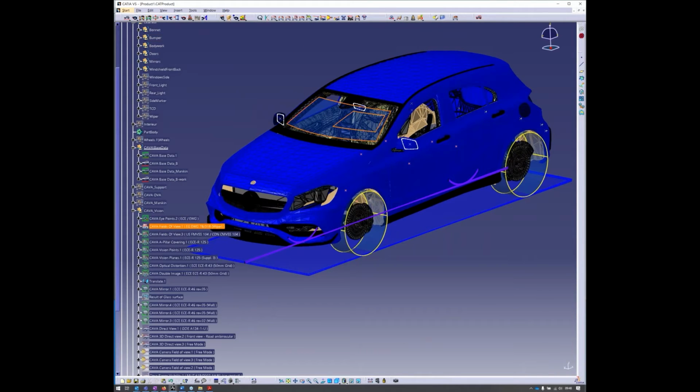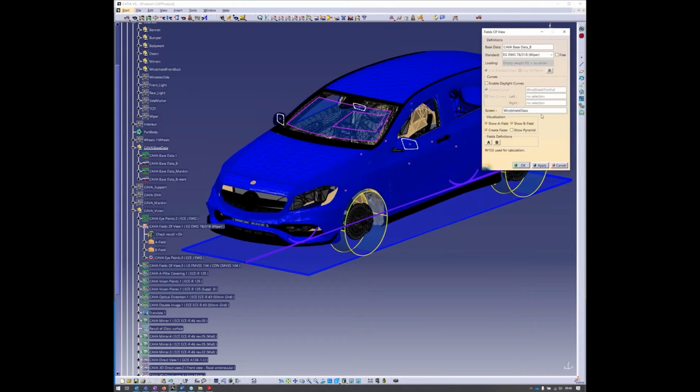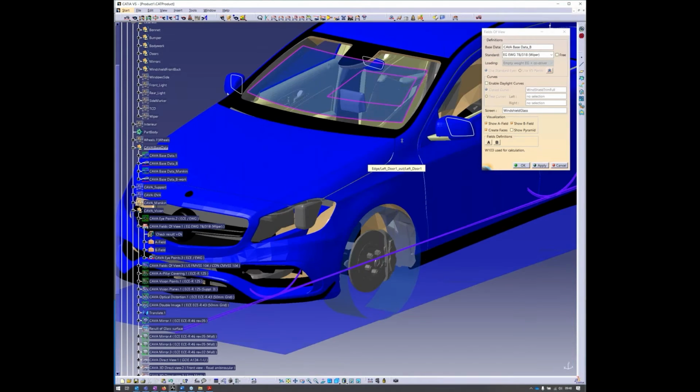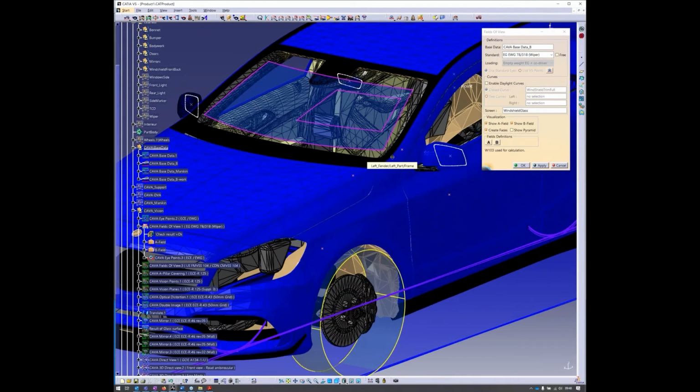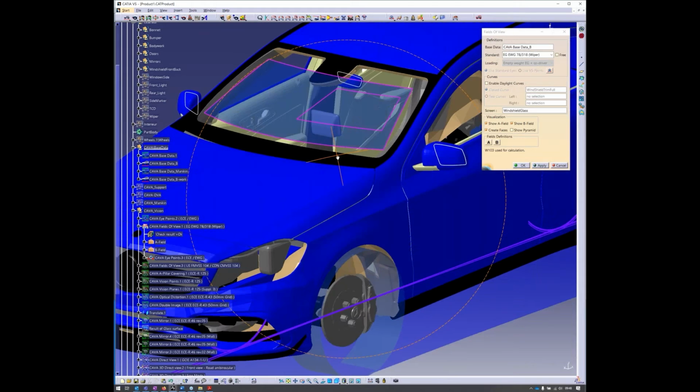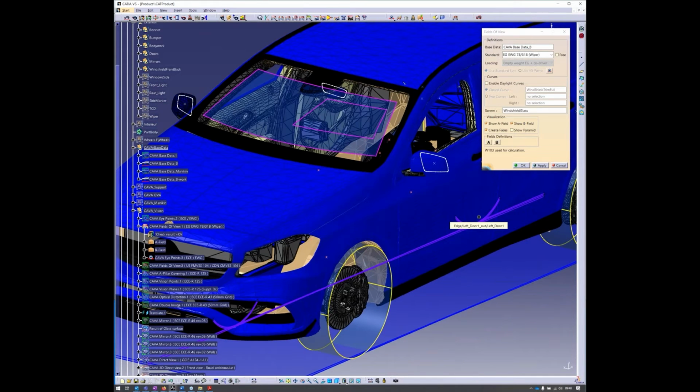Fields of view are regulated in ECE R43 and other EU regulations. It will result in outputs of the A and B field on the windshield, which have to fulfill certain areas. For example, the A field, the small field here, needs to be wiped 100% clear, and the B field would need to be wiped, I think, only 98%. And there are also other requirements in these fields, like the optical properties of the windshield. So it's important to get this information.